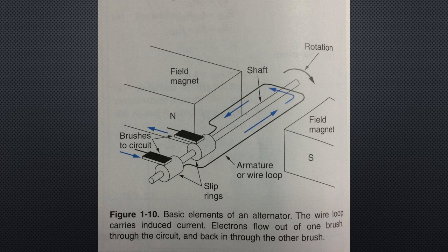Alternators. An AC generator or alternator consists of several parts, figure 1-10. The following is a brief description of four basic parts. First, the coil or armature rotates. Its conducting wire cuts across a magnetic field. The electron flow begins in this part. Second, the stationary poles, sometimes called the stator, create a necessary magnetic field.